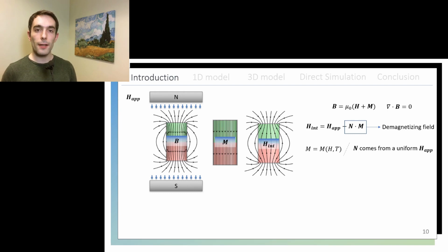Then, when modeling the magnetic field in our regenerator, we should keep in mind three different physical fields. B would be the magnetic flux, which is the variable which obeys the law of continuity you see on the right corner of the slide, and is the summation of the other two fields, H and M. M would be the magnetization of the material, which is the magnetic field created by the sample itself, and H would be the magnetic field intensity, which is the magnetic field created by other kinds of boundary conditions.